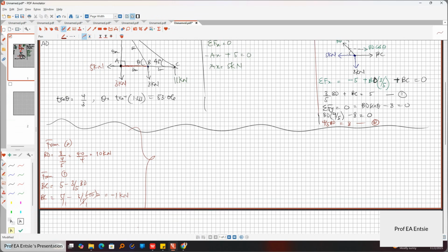In this problem, whatever you do, when you assign a direction to a force and after solving you see the force has a negative answer, you see, force is a vector quantity. So if you get a negative force but you represented it with the right direction, it means the correct direction should be opposite to what you chose at first. So that's what it means.